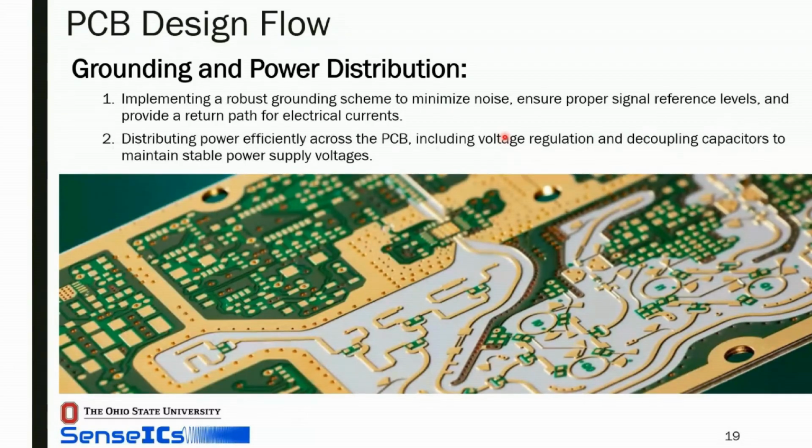So you might have a shunt capacitor that you can vary the width, but you as an engineer still have to do the simulation. The automation aspect, I've never. Mike, have you ever automatically designed an RF PCB? Right. So there are tools to help you, but to automate, those tools aren't super mature, at least from my knowledge.